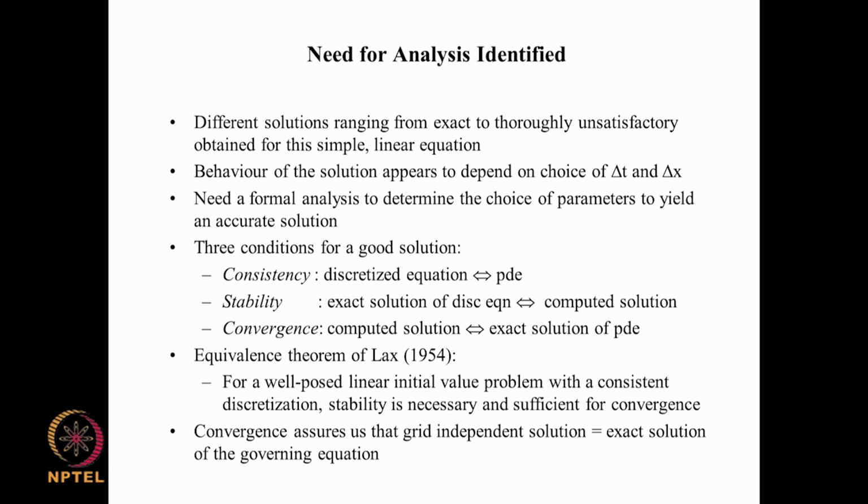So, we have to be clear about this: in a heat transfer problem, we are solving for temperature, and from that we are deducing the heat transfer coefficient. Okay. The heat transfer coefficient is determined by the gradients at the boundaries, and temperature is determined by the corresponding temperature equation, the energy balance equation, which has many more terms and a variation which is different at different points within the domain.